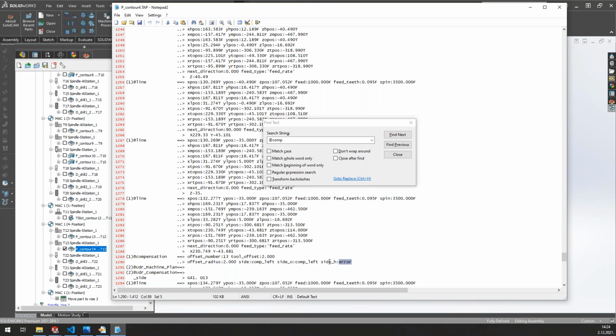So side H will only have a value inside the main plane, let's say like that, of the submachine coordinate system or the virtual mech. Now, where you can use this: let's say you have a table machine and you have the tilting of the plane, and you rotate a part, use the tilting of the part, but still are not inside one of the main planes. Then only side H will tell you that.